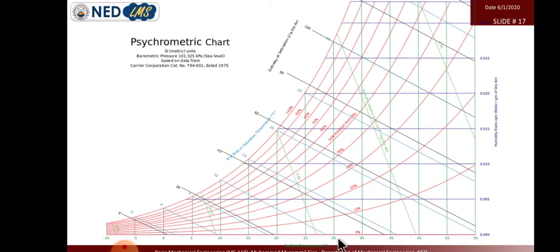So the dry bulb temperature is also cooling. We already discussed what dry bulb and wet bulb temperature are. Dry bulb temperature is the simple normal temperature in which the thermometer bulb is dry, and the wet bulb temperature is when the thermometer bulb is covered with water-dipped cotton.